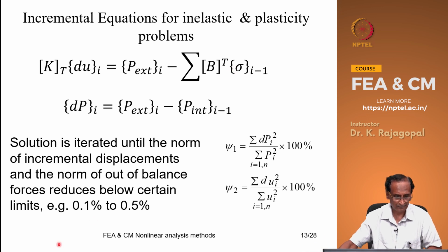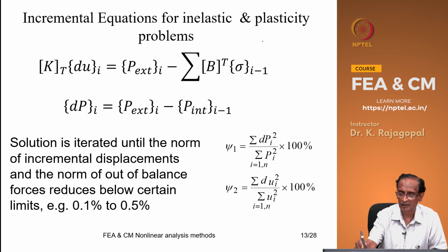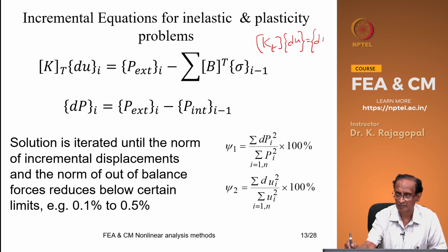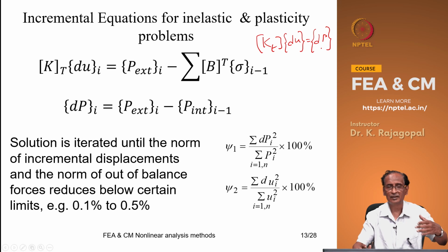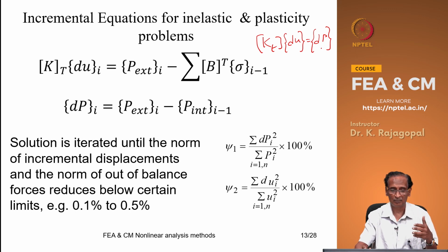Previously we had written the equations like this. We simply wrote the incremental stiffness matrix multiplied by du is dP, and that dP is only the applied pressure, and we did not bother about calculating the reaction forces, because anyway they will be equal to the applied forces.